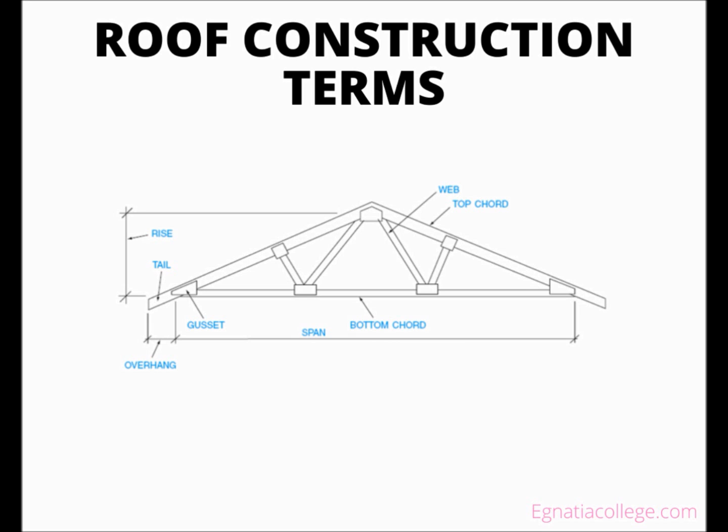The slope of a roof is a way of indicating how steep the roof is. The slope of a roof is usually given as the number of inches of rise per foot of run. This is called unit rise. Another way of stating the steepness of a roof is pitch. Pitch is the rise of the roof divided by the span and is stated as a fraction.